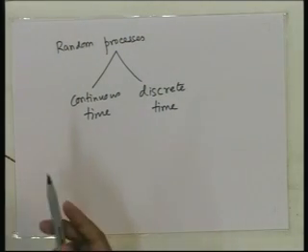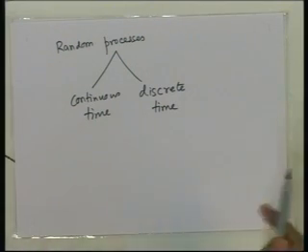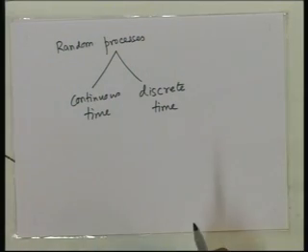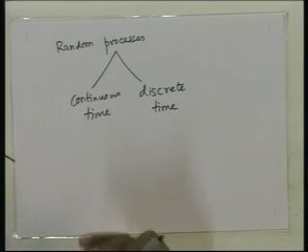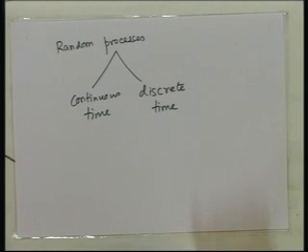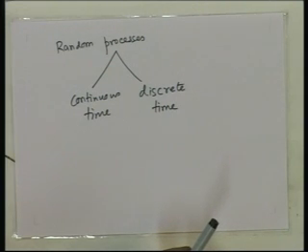If we measure the function for a particular register, if we see what function we get, how the voltage is changing, and if we plot it, then we get one realization of the random process. It does not tell you all that is there about the random process. We are only seeing one particular instance, one particular realization of the random process, or stochastic process. Such a function is also called a sample function. It is like a particular outcome of an experiment. We are not observing all the outcomes, we are observing one particular outcome.